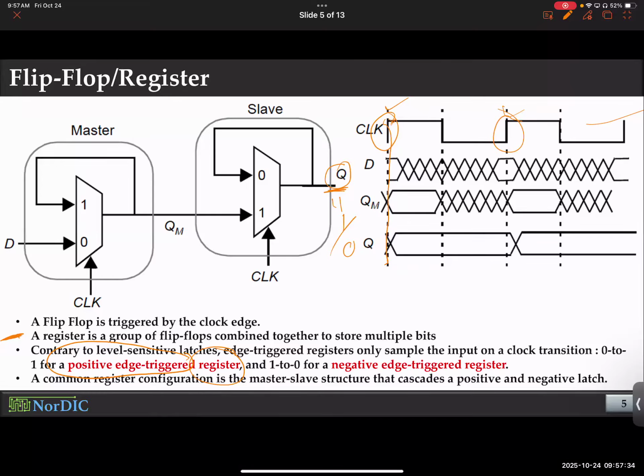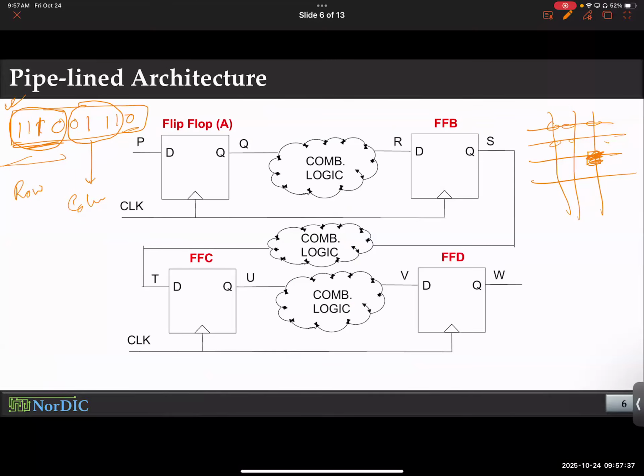Notice, just to do this 1-bit operation, with a super simple example of 4-bit row, 4-bit column, and 1-bit information, you need 9 bits. You need 9 bits to just decide on 1 bit, right? And in practice, it is even more. Okay. So how many clock edges will you need, folks? 9. Because every clock edge sends 1 bit. Are you relating to this? Every clock edge sends 1 bit. So even with this childishly simple example, you need 9 clock edges.